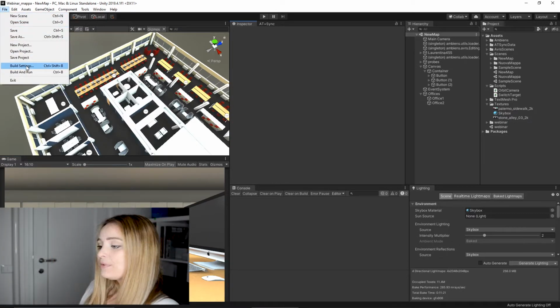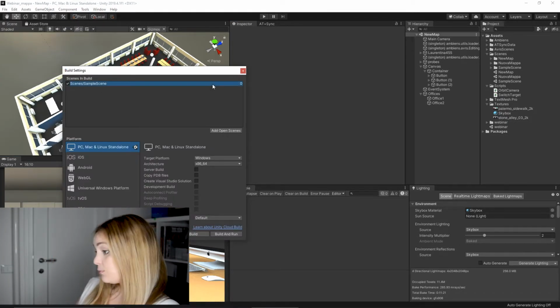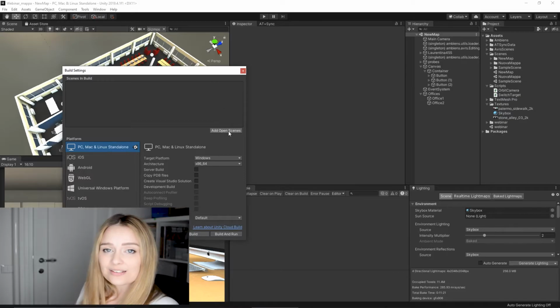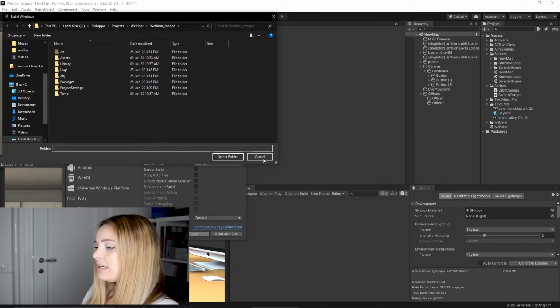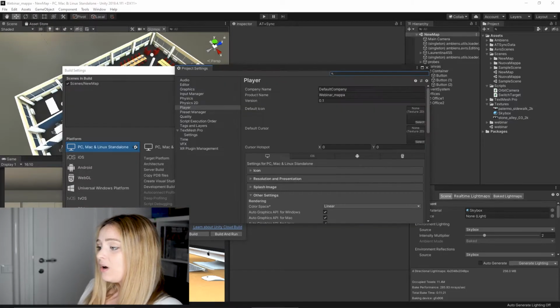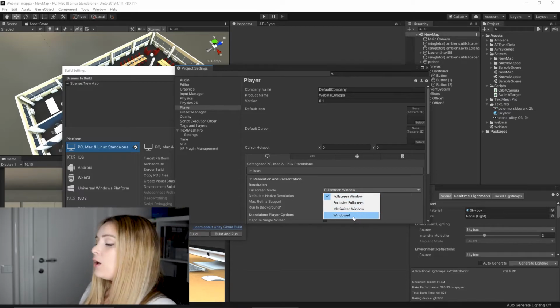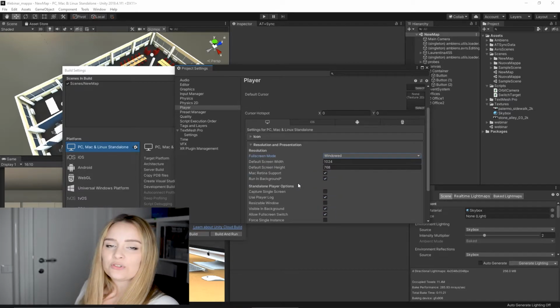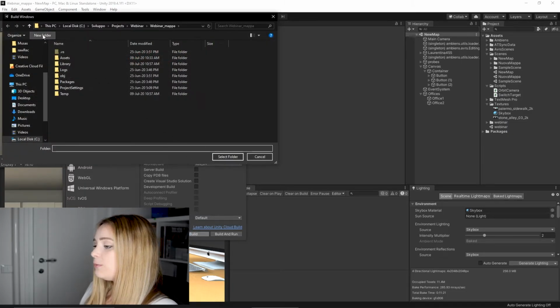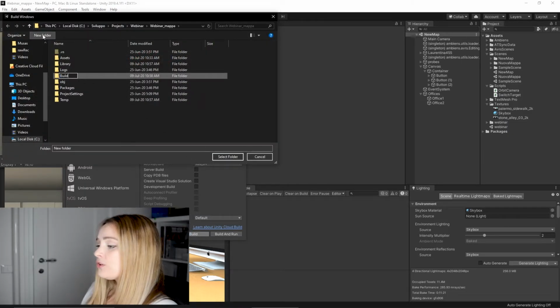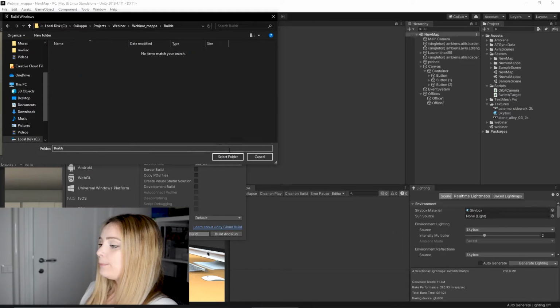The last step is to export this project, so we'll create an application now. With the application, anyone, even those who do not have Unity on their device, will be able to open the output of our project. Just need to set a few parameters, choose a folder for the export, and click Build.